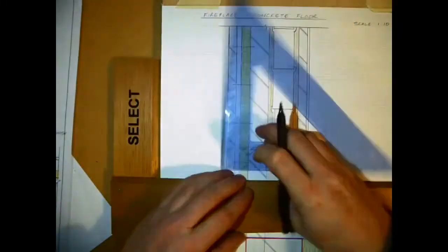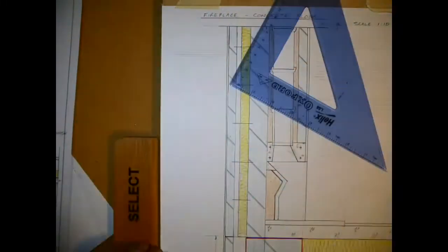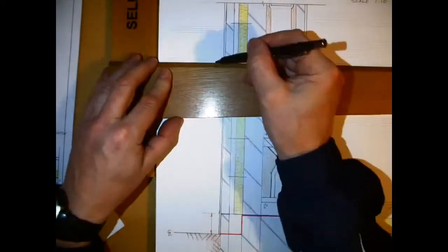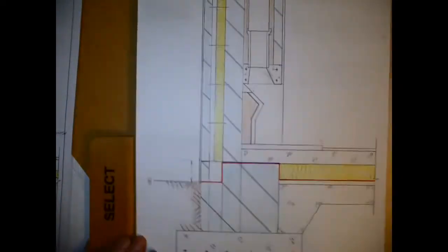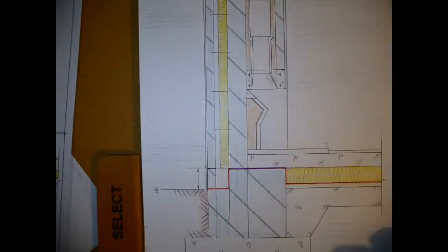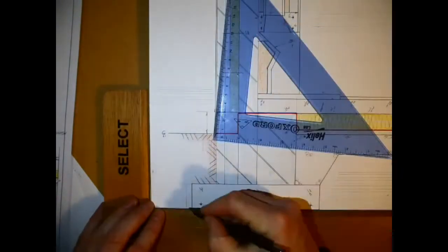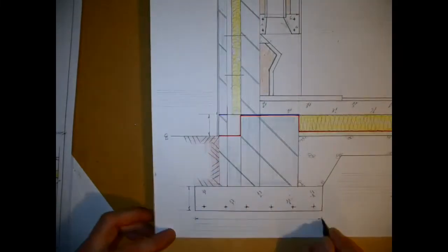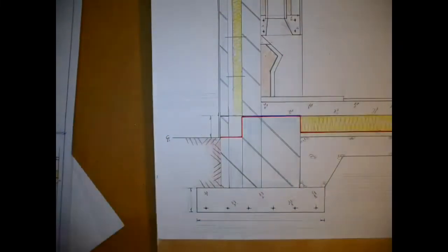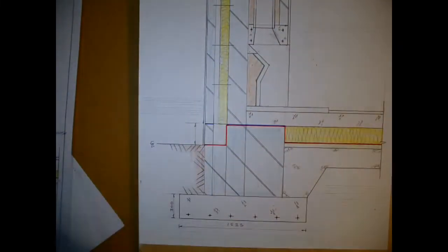And the throat should allow for the gases to easily be carried away. And if there's a bend in the flue, it shouldn't exceed 45 degrees. Some specifications might give 37.5 degrees, but normally it'd be 45 degrees, but it shouldn't exceed that. And it's important to make sure that you put in all your details here. You can stop the video at any stage to look at sizes.